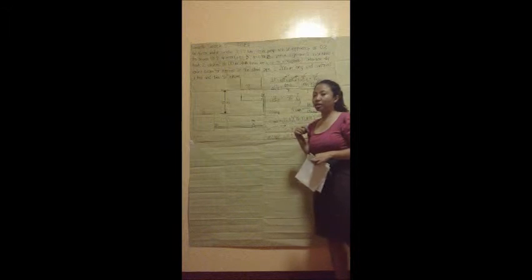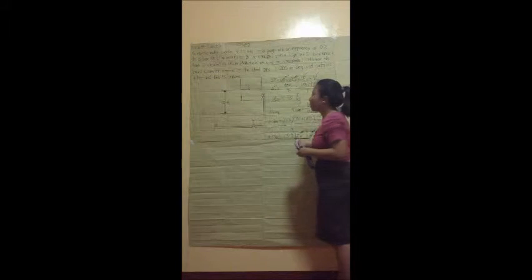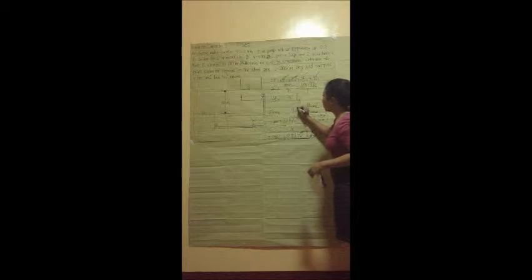Next, we should get the shaft work made to the pump. What is given is only the actual power, so we need the ideal power in the mechanical energy balance equation. Remembering the formula for the efficiency of the pump, which is W ideal over W actual, we can now solve for the W ideal since we are given the efficiency of the pump and the W actual.